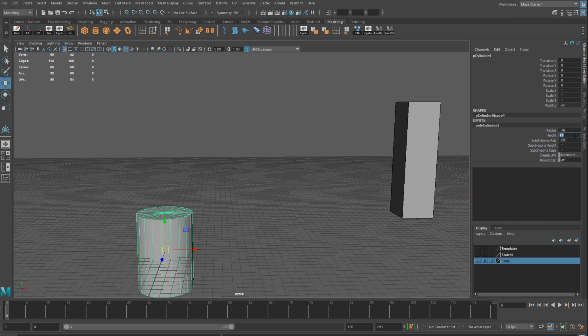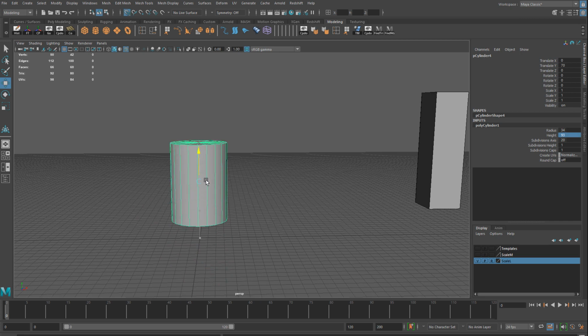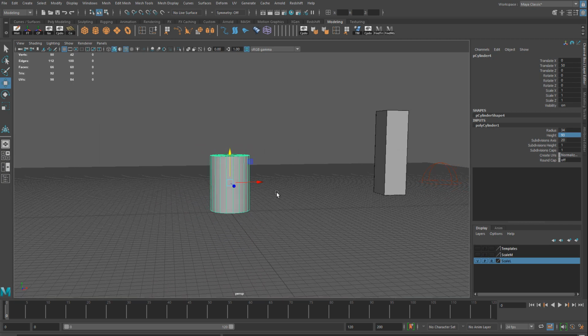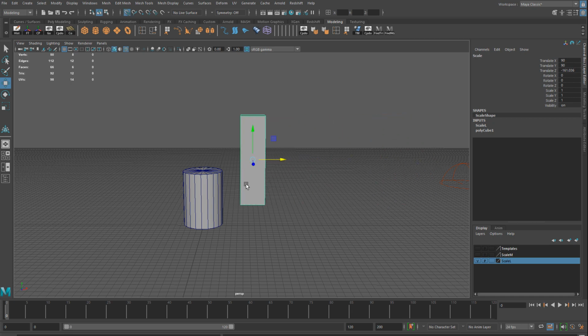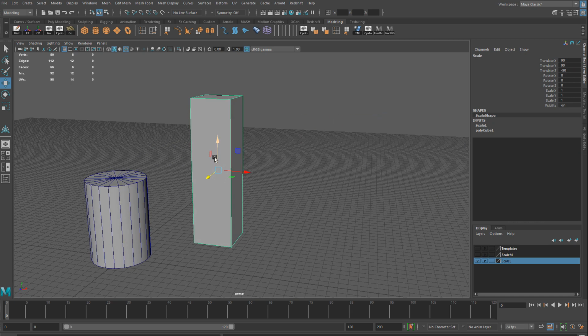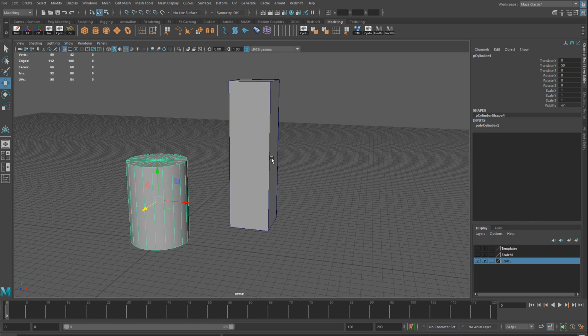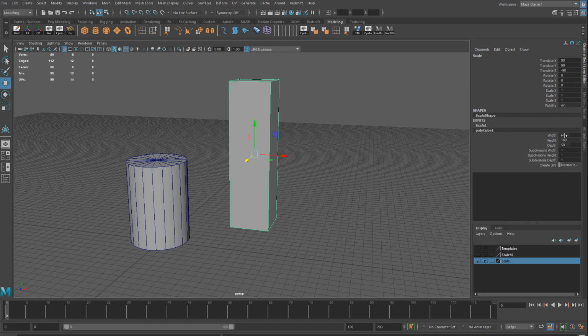So I'm going to punch in the values that it gave me from my dimensions, but then I'm going to adjust it. Now let me go ahead and move this scale box right in here. So this scale cube is a way for me to judge proportion and dimensions of my objects, of environments that I create. And this cube is set to 50 by 50 in width and depth, and 180 in height. So this is about 6 feet. And these are the dimensions in Unreal Engine 4 for a basic standard human height reference. So let's go ahead and I'm going to lock it back up.